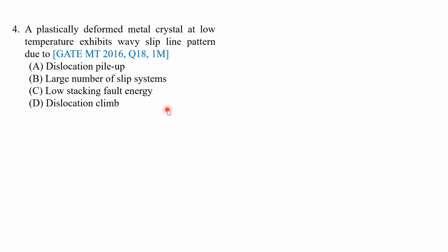So, next is stacking fault energy. What is meant by stacking fault energy? Stacking fault energy is a material property on a very small scale and it is the energy per unit area. We know FCC, BCC, etc. have a particular stacking arrangement, like ABAB, ABCABC, and so on. Whenever there is a disruption in this particular stacking, it gives rise to the stacking fault energy.